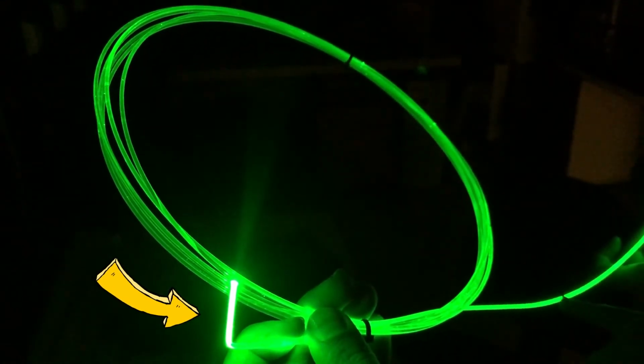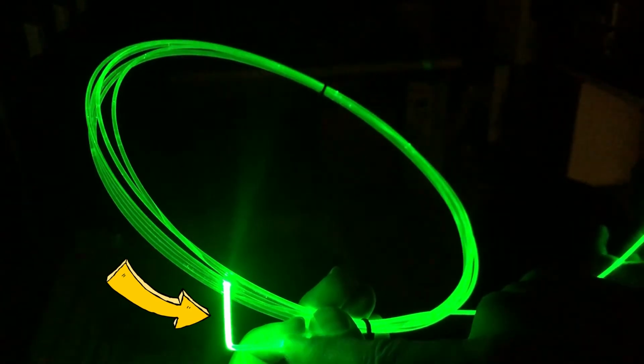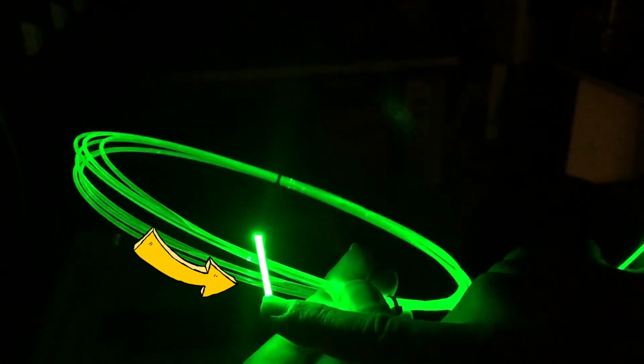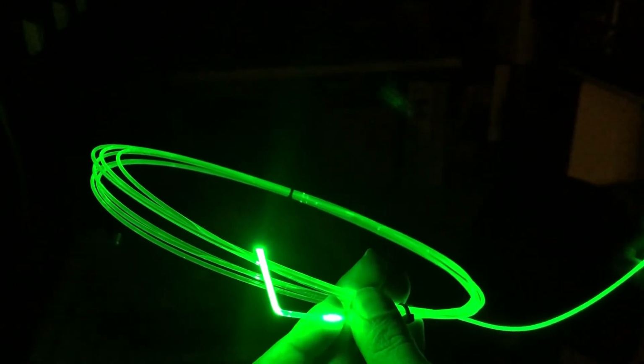To observe the external attenuation, the polymeric optical fiber was utilized, which was bent at the end. When the light reached this segment, there was a big intensity loss, and it was possible to watch a strong light emission. This effect happened because the light, when it reached the bended part, started to travel at a lower angle than the critical one, which caused the scattering and transmission of the light after the segment, and it was responsible for signal attenuation. To observe the cladding effect on critical angle, materials with different refractive index were used.